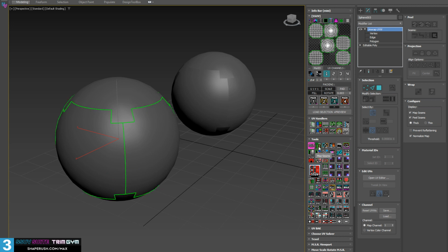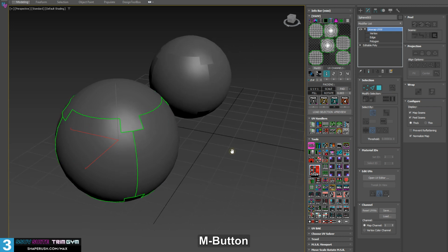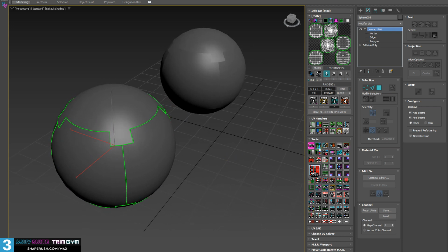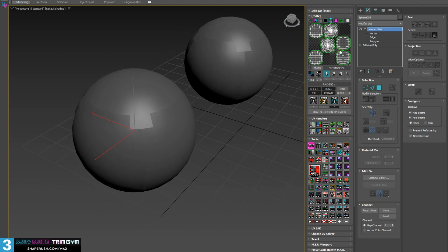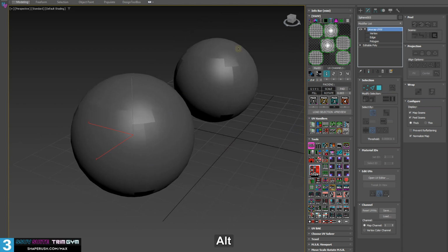Now, with the seam setting, we can left click and toggle through various states. Okay. But that does not update the rollout here for the unwrap modifier. However, if we do turn this off, and we load the object back into the system, we see that the seam settings are turned off, even though they are displayed here.